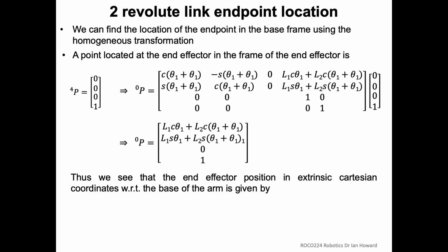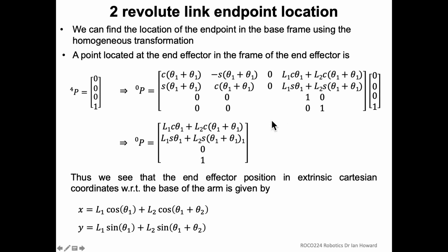And that's effectively giving you forward kinematics. Right? You give it the theta. L1 and L2 are fixed, and there you have it. I think they're all theta 1 for some reason. Maybe that's something wrong. I think there's some of those should be theta 2s. So we see that. Yeah, definitely. So this is correct. That's wrong. So we see that the endpoint then, the x and the y values are given by L1 cos theta 1 plus L2 cos(theta 1 plus theta 2), and so on, which you can also derive. In fact, we've done that kind of derivation in a more simple way by hand before.